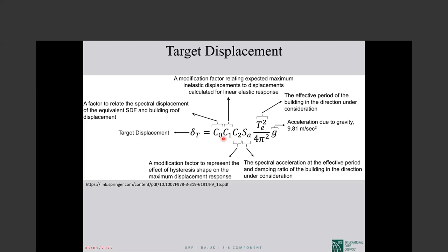If the drift increases from story 1 to the upper ones, it is bending. If it decreases, it is shear. Then we can use those tables and find the C0.